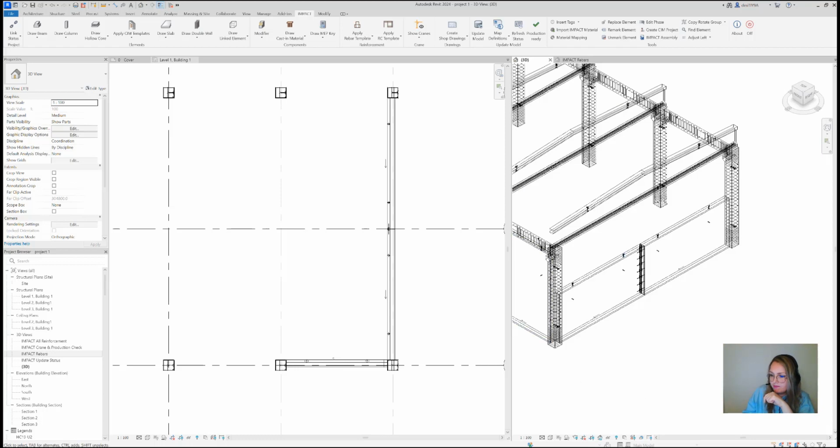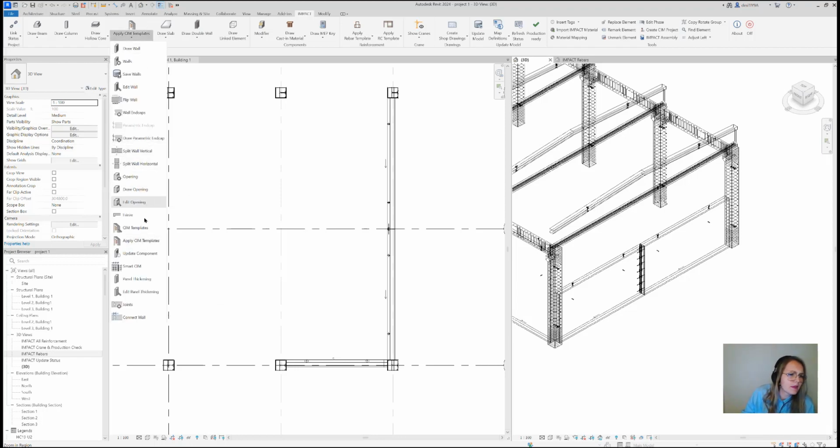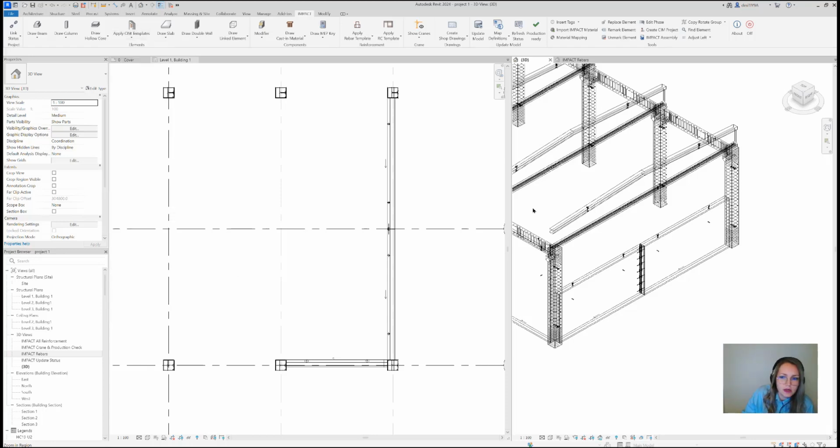Okay. We talked about the casting material templates, and now I think it's time to do some openings. If you do walls, you can't go without it. You need to do some openings, and we have a draw opening command and edit opening command in the wall folding menu.